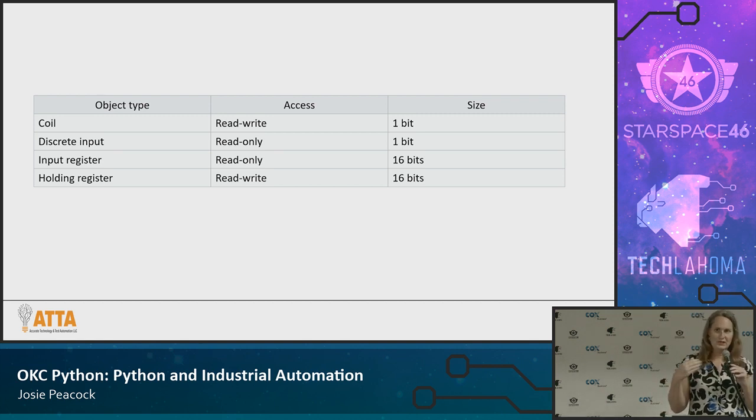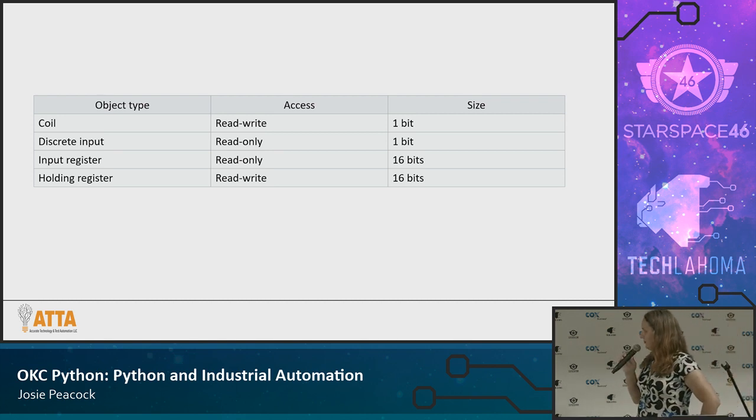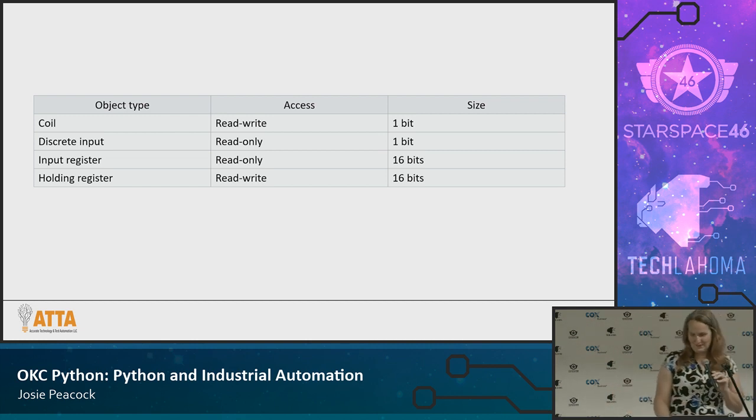You can normally only pass 16 bits at a time maximum, which proved to be a real challenge with some servo motors I worked with. The resolution actually pushes 64 bits back through, but you have to get that 4 registers at a time. Then you have to piece that back together to decide what the position is, which is just loads of fun, especially with somebody who's a little dyslexic. So get everything tied right.